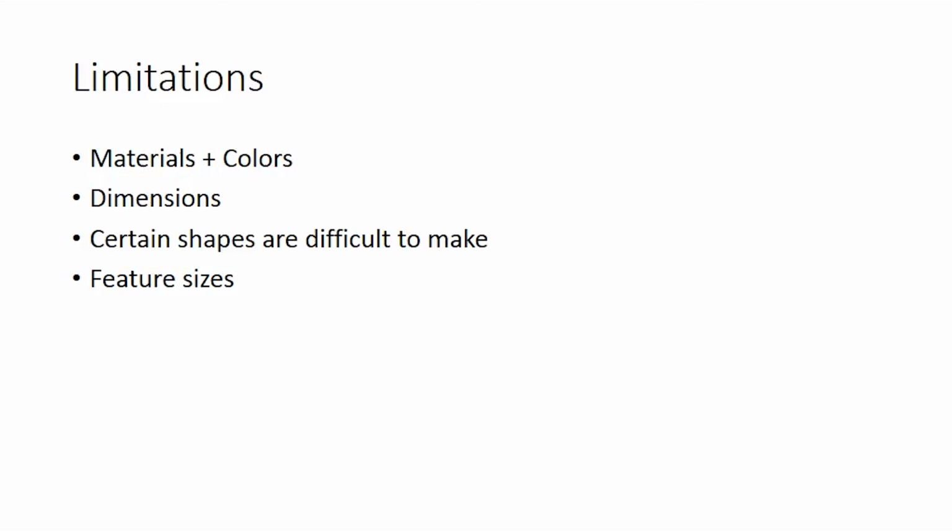Because you might say, like, oh, I want to make a tiny robot fly or something like that. And you're probably not going to be able to print all that fine detail on a machine like this. Now, if you had an SLA printer, for example, like the Form 1, which uses photo-curable resin and a UV projector to make the parts, you could get very, very high precision parts, like down to 5, 10 micron precision. This thing, the minimum layer height is 50 microns. So that's half of a tenth of a millimeter. But that's still not that small when you're working with tiny gears and stuff like that.